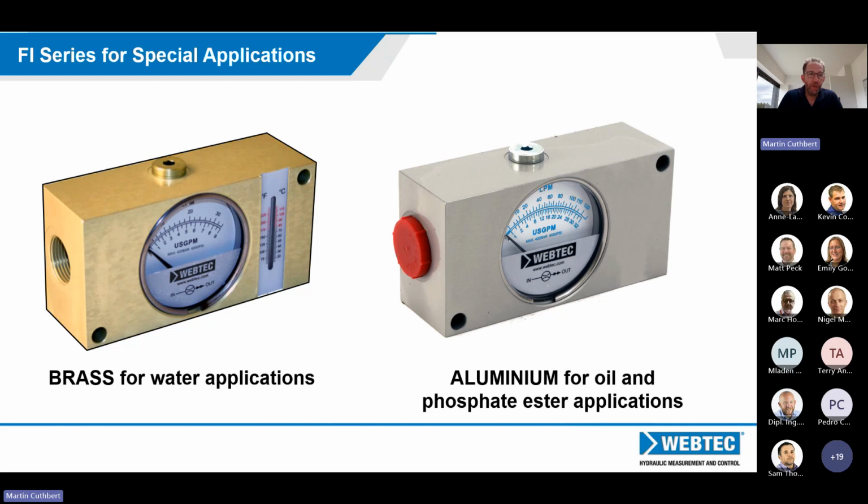So here's two examples of instruments you might use for monitoring of coolant flows. So if it's high pressure water coolant or a water glycol with a very low viscosity, then that unit on the left there is a brass unit for water applications. As you can see, very similar to the design of the aluminium one you saw beforehand, still measuring flow, temperature, joule scale, no batteries, using pressure drop to move it, and it has a blanking plug on top, so you could fit a pressure gauge.